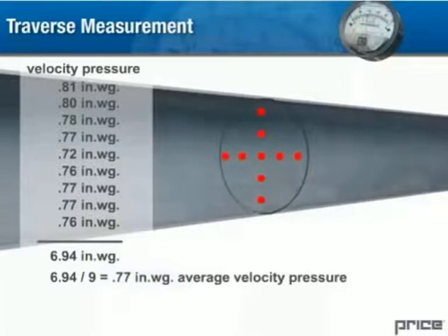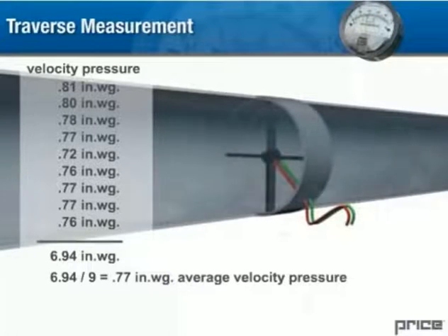In a functioning HVAC system, we would make use of the Price SP series pressure sensor for measuring air pressure at terminal units. It is superior to the pitot tube in that it automatically receives representative pressure samples from across the cross-section of the duct and automatically averages them.